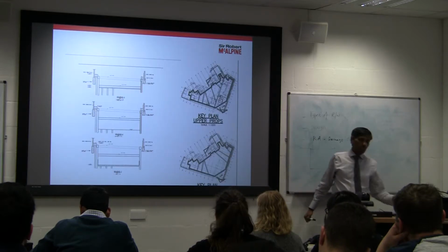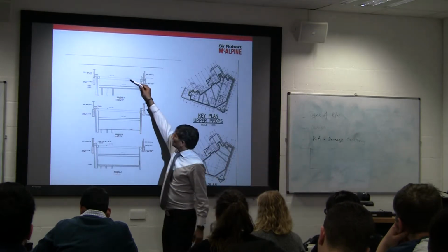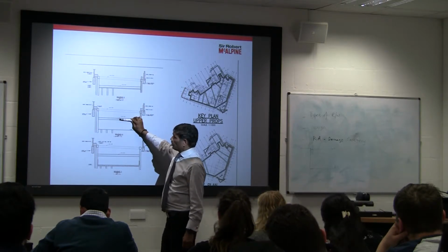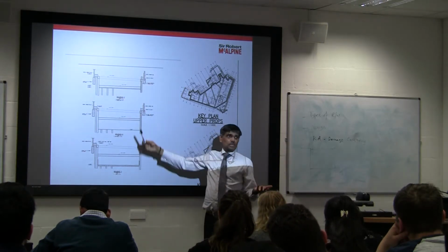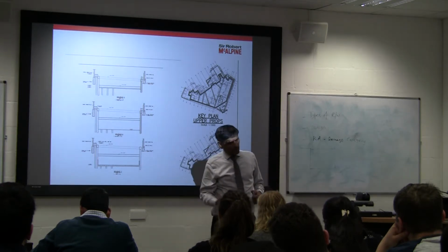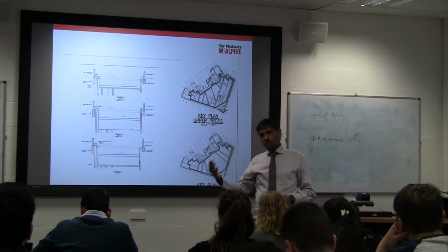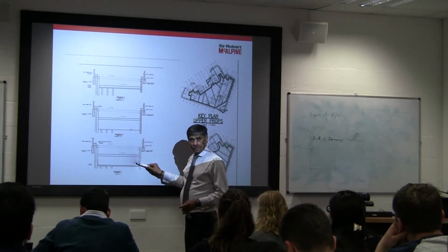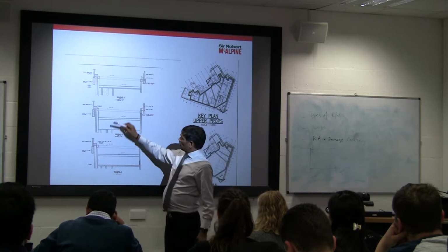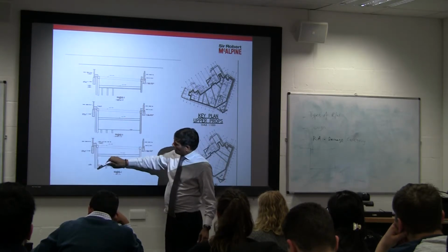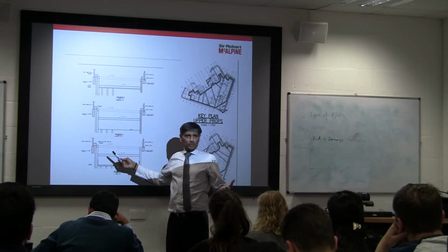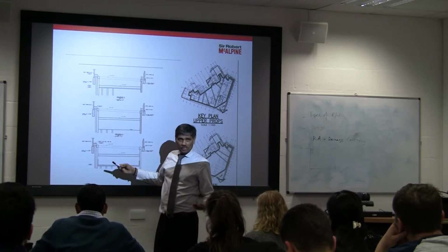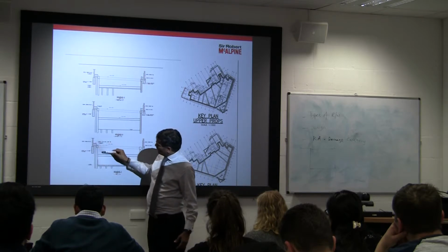next stage it shows you how we go sequentially. So we put the prop already, so now we can start digging around. And then a second level of prop if it is required. Sometimes, remember I told you about the depth of the foundation and also the adjacent structures. You have to decide how many props you have to put here. It is limited by, obviously, if you leave this, the bending moment on this is going to be huge, because the forces are coming this way. Imagine this is like a simply supported beam. So the bending moment diagram will be that.